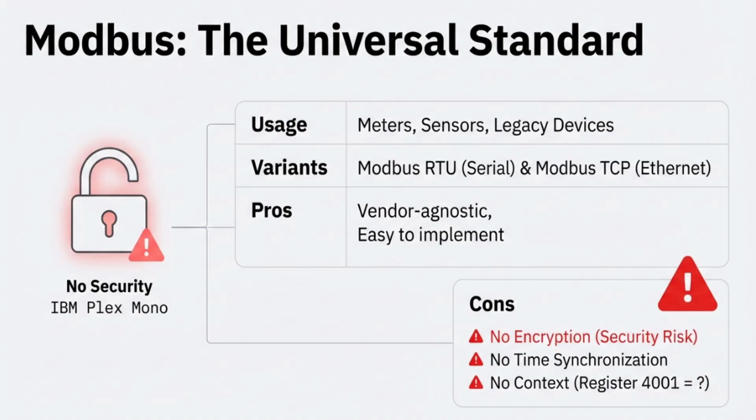When a bad actor can fetch this, it will be problematic, right? That was the biggest concern we have in Modbus, because we don't have any encryption. This is essential as of now, and as per compliance also, we need to implement encryption, right? That is one of the major drawbacks we have in Modbus.